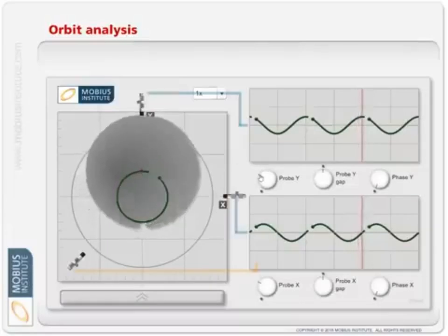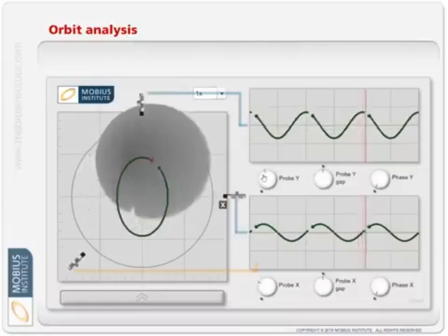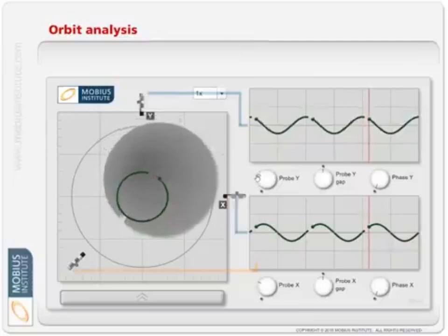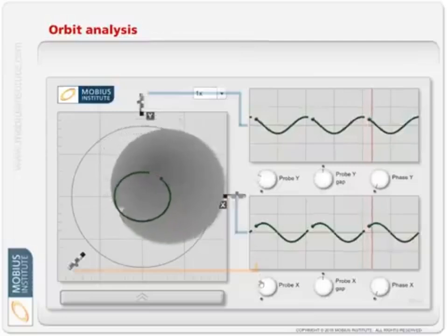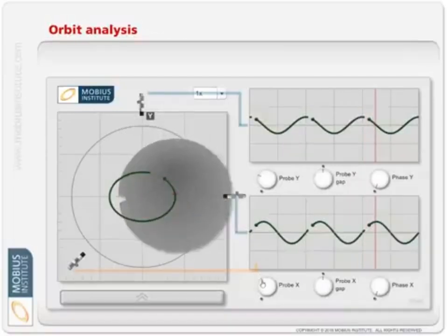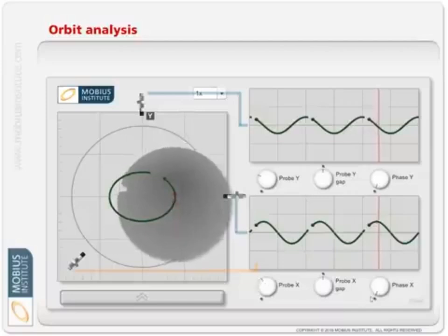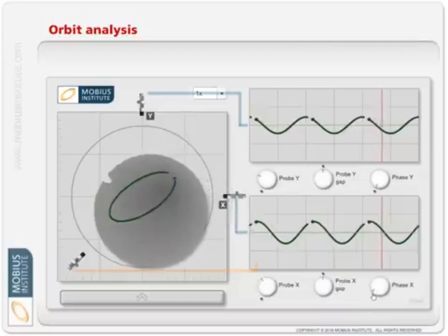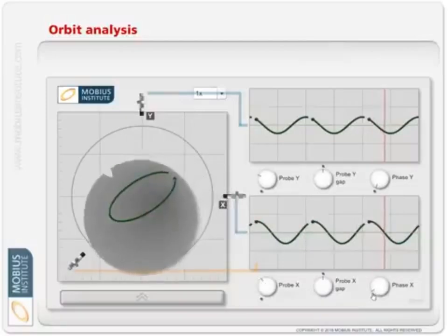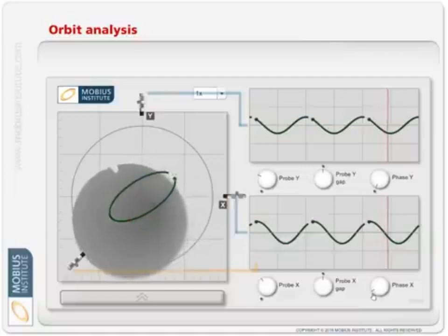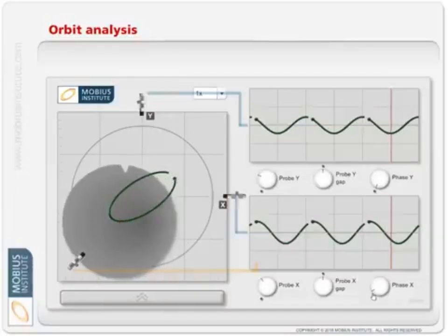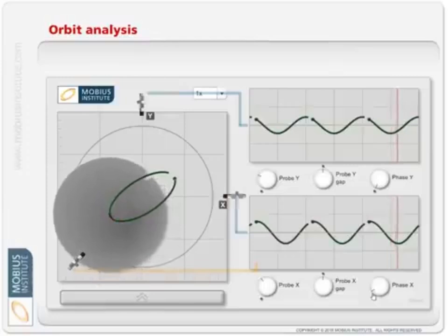So for example, we may see more vibration in the x-axis because of the loading, and maybe it's got elliptical bearings. We can see interesting phase relationships. We can see all kinds of things depending upon what's happening with our machine. It's a really useful measurement, and there are other measurements we can take on these sorts of machines as well.